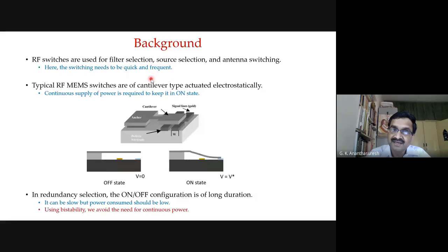If that is the case, using thermal actuation might not be good. Then you need electrostatic, which can go to gigahertz frequency of operation. But then force will not be much to make a good contact with the switch. If it is milliseconds or slower, you can use electrothermal. And there are usually cantilever type of switches. If it is here, you have an electrostatic actuator, let's say, it attracts and it will come and close the switch.